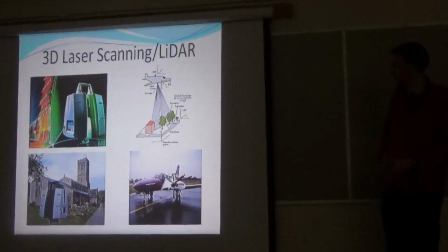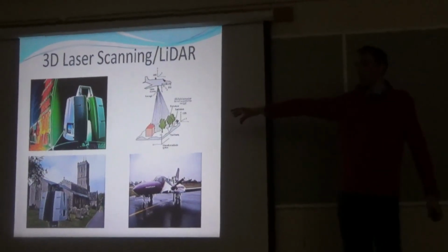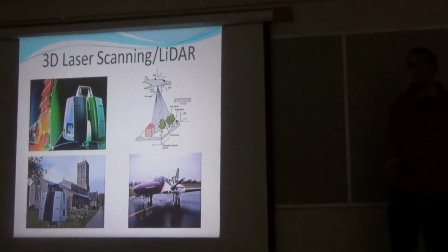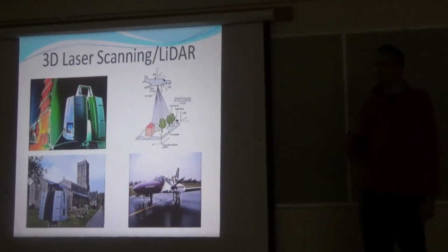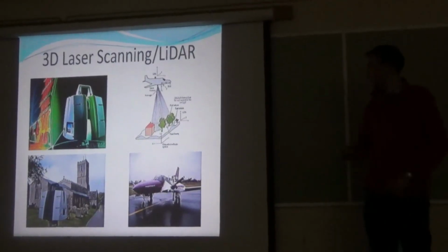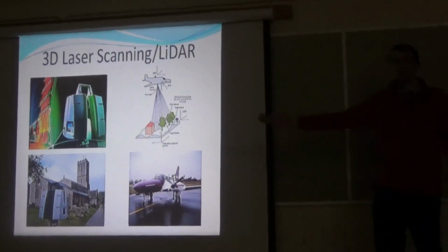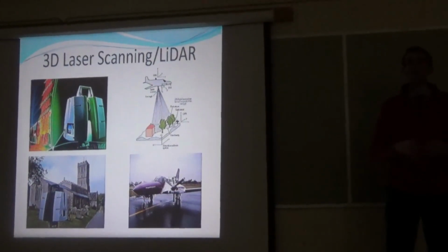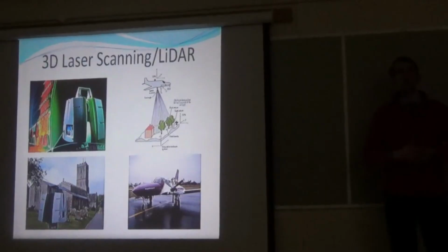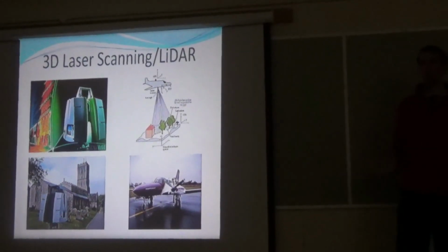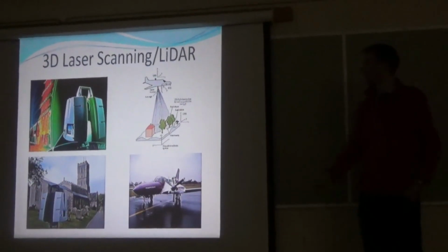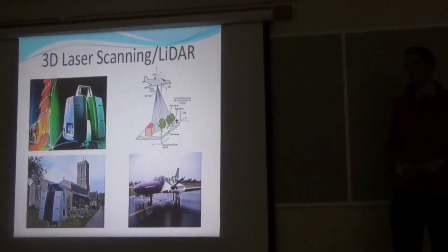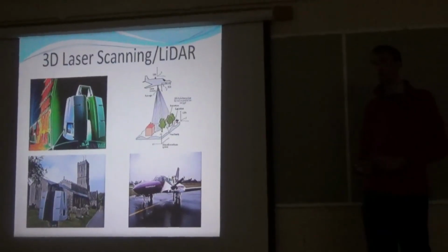With the terrestrial laser scanner, the one for scanning buildings, we're getting 3 mil accurate data. So we're getting extremely accurate data. For looking at buildings, it is brilliant. It's much easier. If we did a building survey by hand, let's say of this room, and measured in all the light fittings, all the screws and everything else, it would take us hours. Stick a 3D laser scanner in the middle of it, one scan would do it. It would take less than 5 minutes.